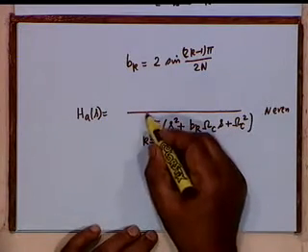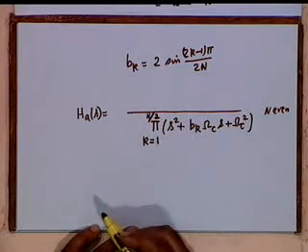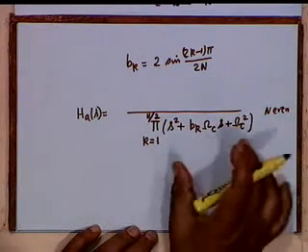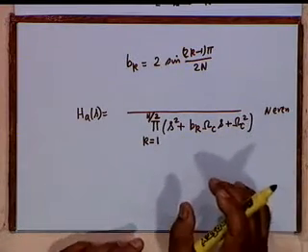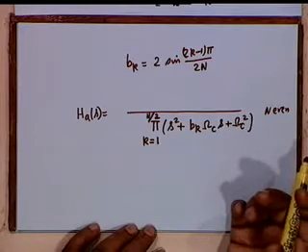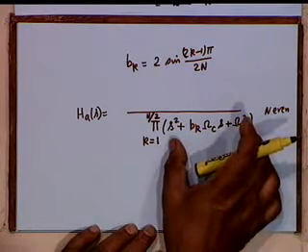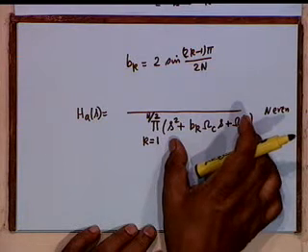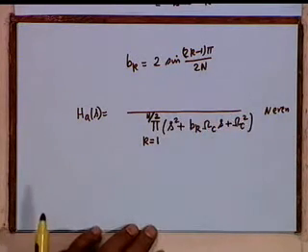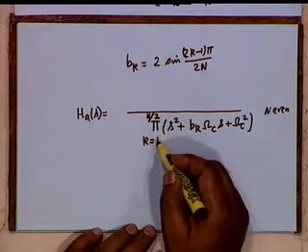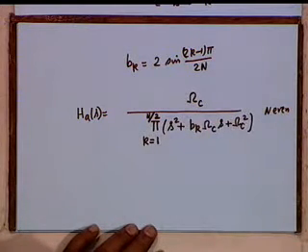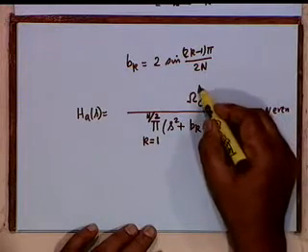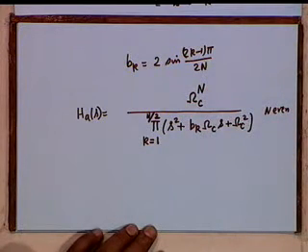Capital N is even, not n minus 1, n by 2, right? There should be capital N number of complex poles, and complex poles occur in conjugate pairs. One conjugate pair is taken care of by this factor. So, there are only capital N by 2 conjugate pairs. So, this is a continued product from k equal to 1 to n by 2, and the numerator shall be omega c to the power how much? N. Omega c to the power n.